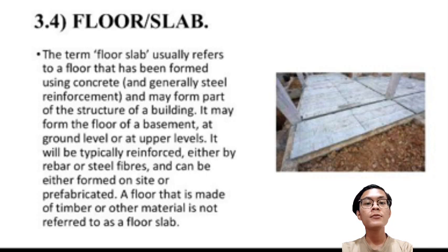Floor slab. The term floor slab usually refers to a floor that has been formed using concrete and generally steel reinforcement and may form part of the structure of a building. It may form the floor of a basement, at ground level or at upper levels. It will typically be reinforced either by rebar or steel fiber and can be either formed on site or prefabricated. A floor that is made of timber or other material is not referred to as a floor slab.